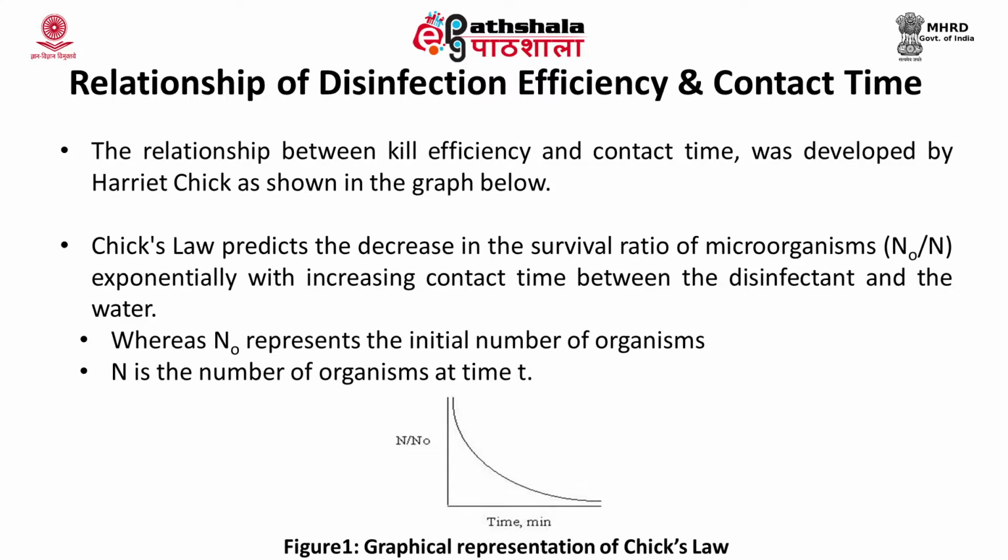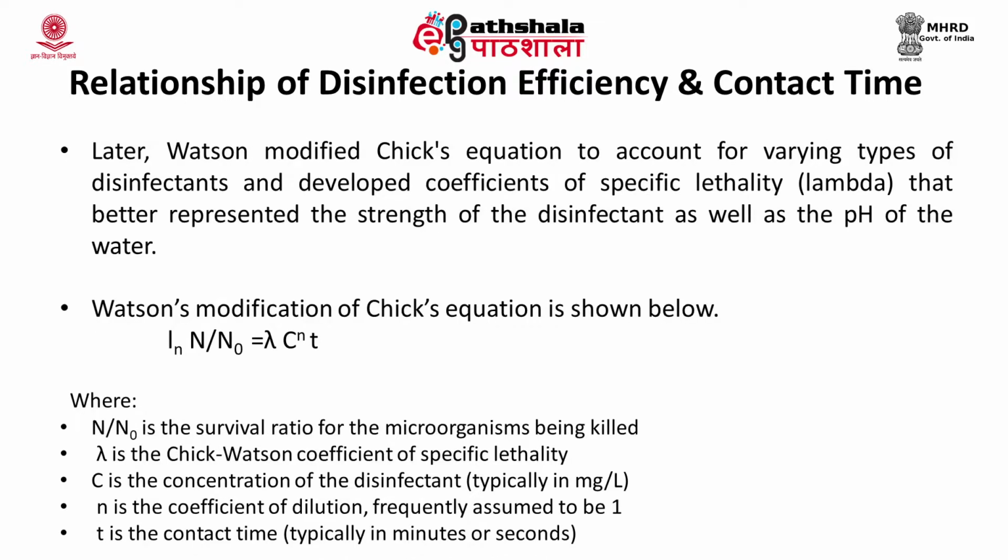Chick's law predicts a decrease in the survival ratio of the microorganisms, which is shown on the graph on the vertical axis, exponentially with increasing contact time between the disinfectant and the water to be disinfected. Later on, this Chick's equation was modified by Watson to account for varying types of disinfectants, and he developed the coefficient of specific lethality, which is denoted by lambda, that represents the strength of the disinfectant as well as the